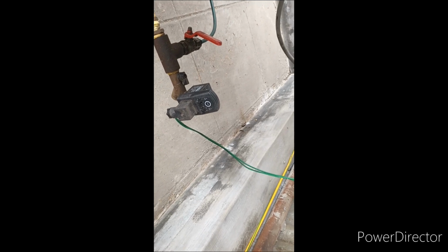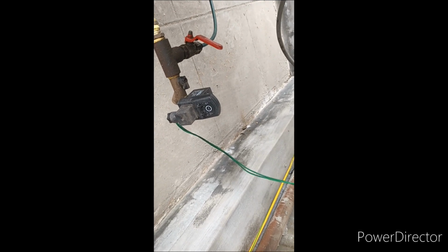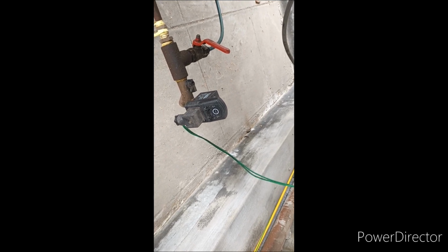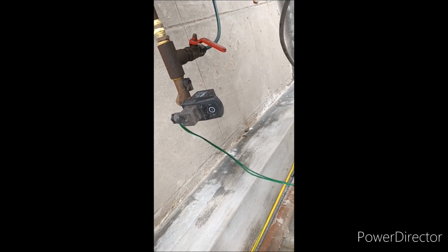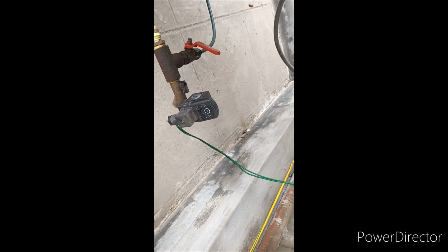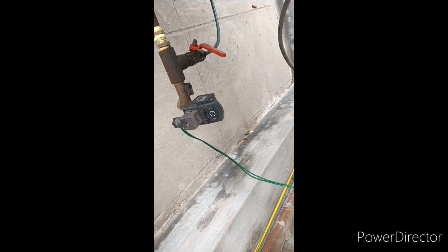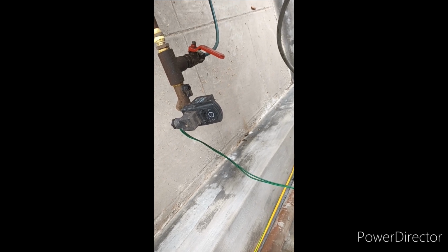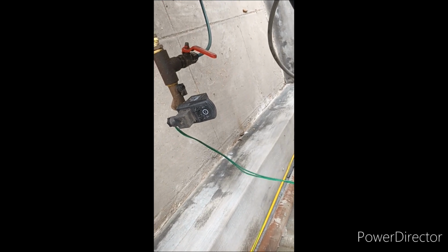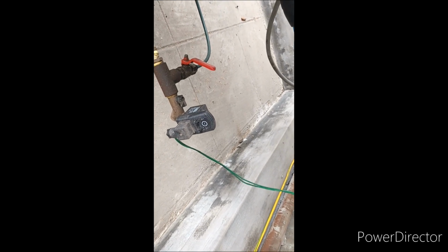The rest is separated from the dryer. To remove the moisture and condensation water from the air receiver tank, we need to maintain it regularly. Condensation is a common problem in all compressors. If the moisture is not drained on time, it can cause corrosion in the air receiver tank. It reduces the capacity of the tank, and the corrosion enters the compressed air, which reduces the life of your air tank and is very harmful to the end application.